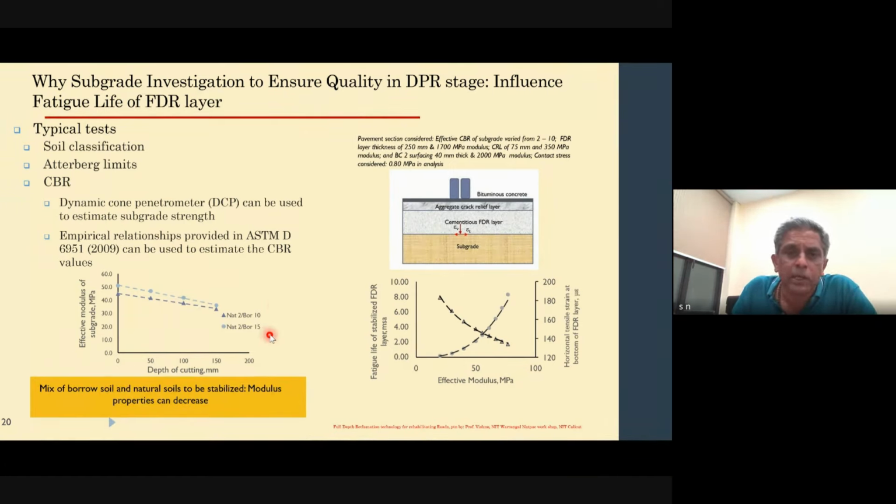Now, the additive requirement is earlier estimated as 0.4 kilograms per square meter. Along with that, you have 40 liters of water per square meter that needs to go in. So how much additive needs to be estimated per liter of water? That is 0.4 by 40, which is about 0.01 kilograms per liter.